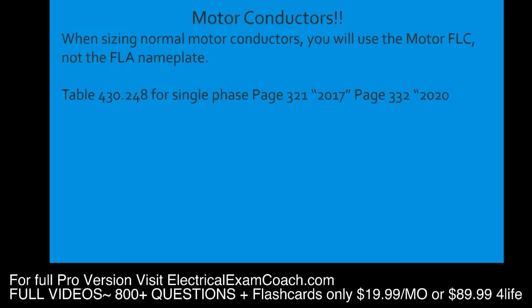So the first thing that we do when we get to this table is we read the black bold heading. It says full load current in amperes for single phase alternating current motors. Great, I feel like we're in the right table. I would go ahead and take a moment, and if you can, highlight that right there where it says full load current, and then highlight the words single phase. Okay? Highlight full load current and single phase.